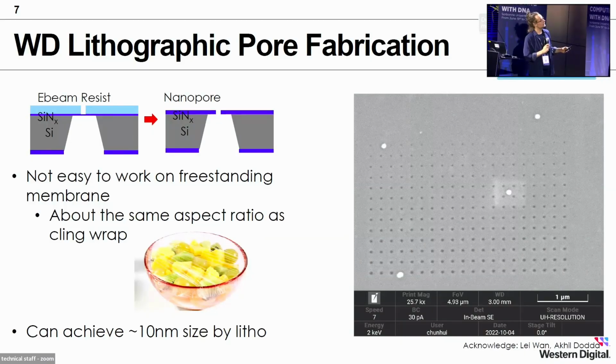So we start with our membrane. We drill holes into it. Here we have a lot. We were testing how small we can make them. And by normal e-beam lithography, we can go down to around 10 nanometers. There are other techniques with dielectric breakdown where we can make kind of arbitrarily small pores down to single-digit nanometers. That's very impressive. It's a testament to the qualification of the fabrication engineers here.